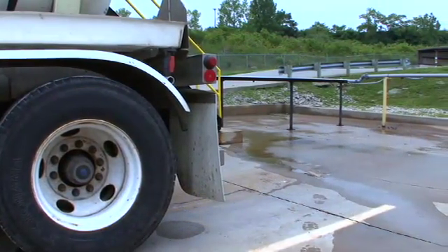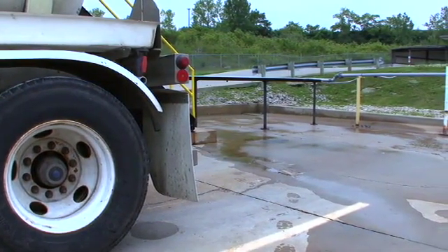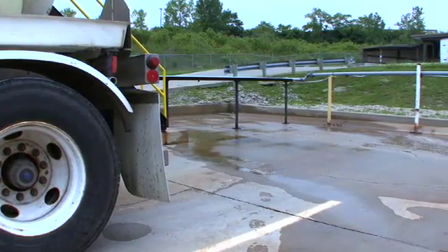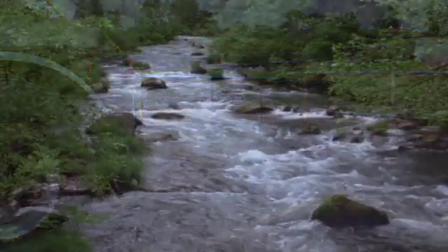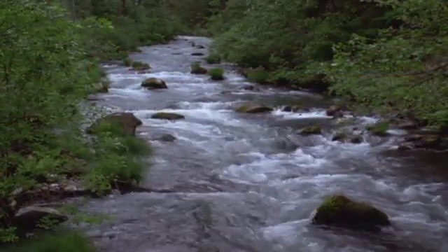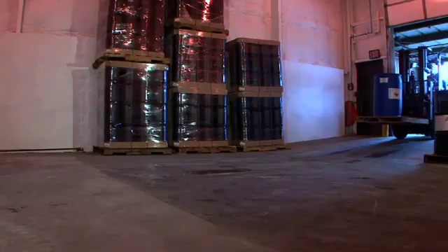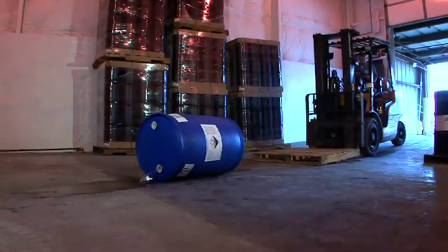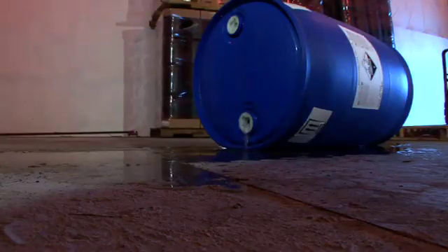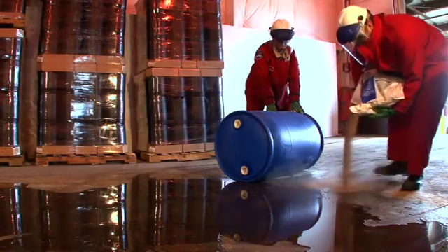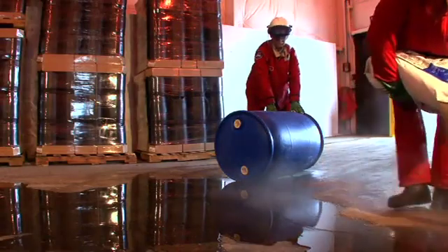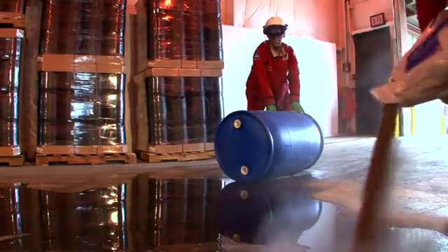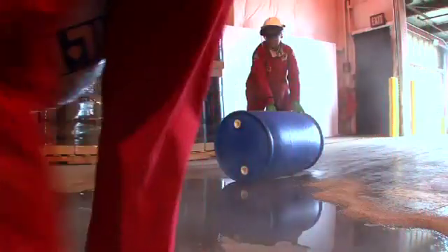Due to strict spill reporting requirements, it's recommended that transfer operations occur within areas with spill containment. Sodium hypochlorite released into waterways can be extremely toxic to wildlife, and especially fish. Even when operators follow established procedures, a spill or release may occur. Whenever sodium hypochlorite has been spilled in a non-containment area, immediately find a way to contain the chemical, such as building a dike out of sand or other absorbent materials such as granulated clay.